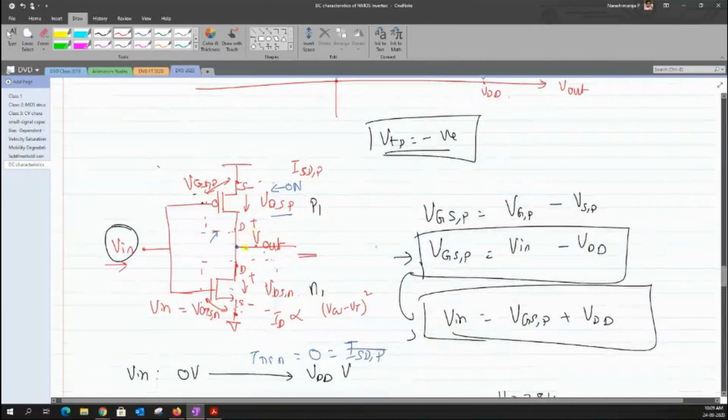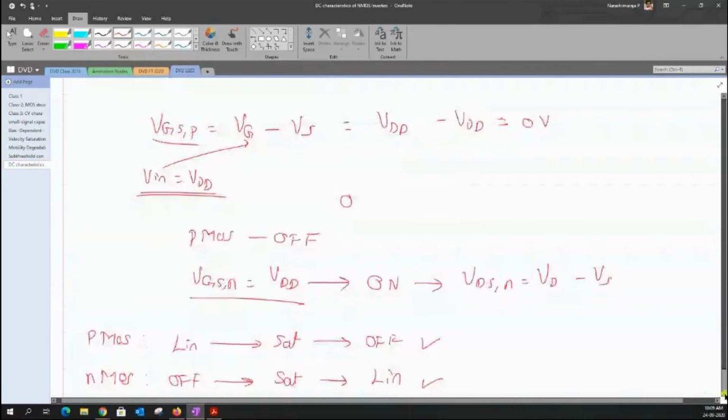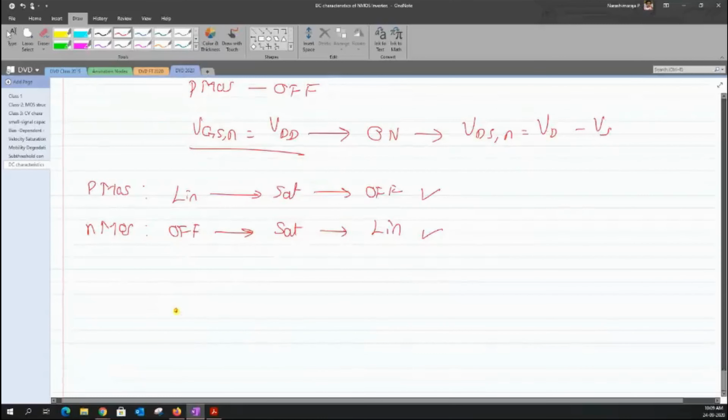Yeah, the output will never float actually. Because for the corresponding value of VGS, we need to have some sort of potential drop. In order to conduct current, because both the transistors are on, it cannot float. Both the transistors are on, and it has to conduct some part of the current. So there's supposed to be some potential difference between the supply, VDD, and this node, which is Vout, such that it conducts a current. So it cannot float actually.